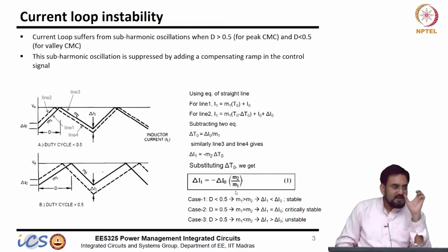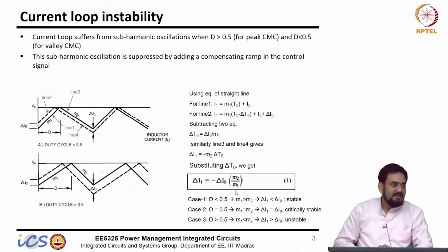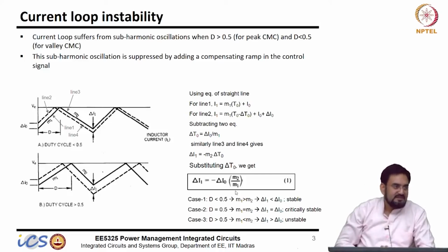See, I don't want to disturb the inductor current, but remember I am sensing the current. So I can change the slope of the sense current without disturbing the actual inductor current. Ultimately I am feeding the sense current, correct?